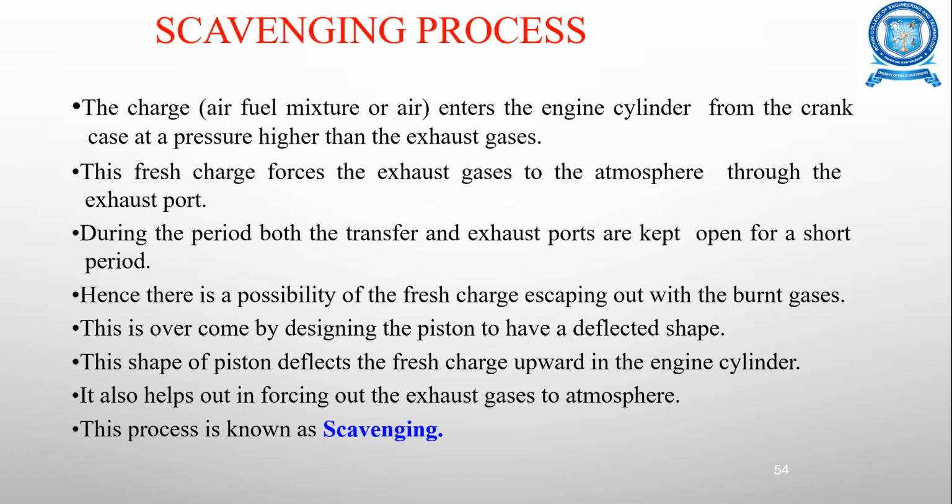This deflected shape of the piston deflects the fresh charge upward in the engine cylinder, and it also helps in forcing out the exhaust gases to the atmosphere. This process is called the scavenging process.